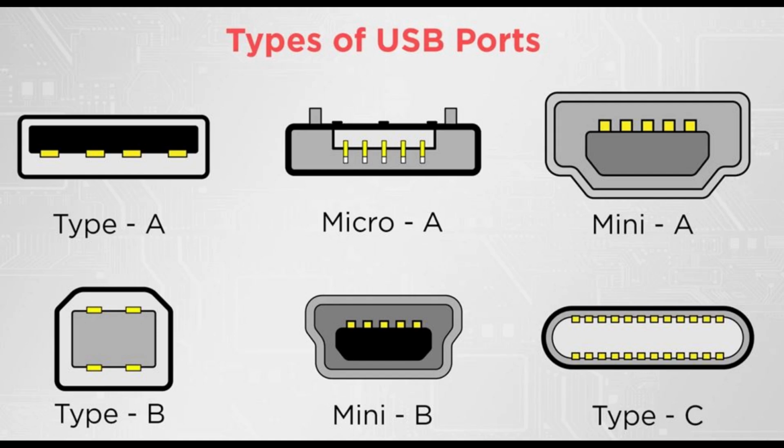The USB 3.2 specification added a second lane to the enhanced SuperSpeed system besides other enhancements so that the SuperSpeed Plus USB system part implements the Gen 1x2, Gen 2x1, and Gen 2x2 operation modes. However, the SuperSpeed USB part of the system still implements the 1-lane Gen 1x1 operation mode. Therefore, 2-lane operations, namely USB 3.2 Gen 1x2, 10 Gbit/s, and Gen 2x2, 20 Gbit/s, are only possible with full-featured USB-C. As of 2023, they are somewhat rarely implemented.